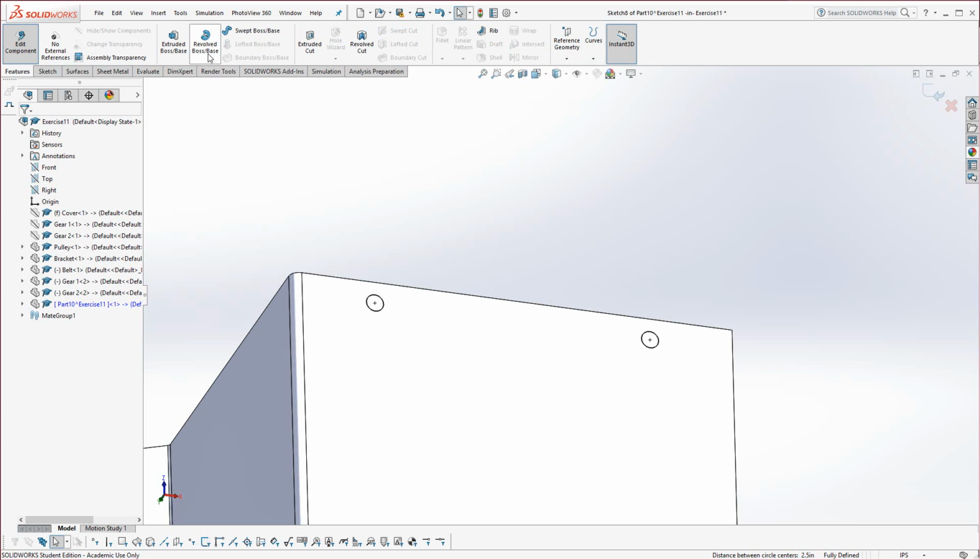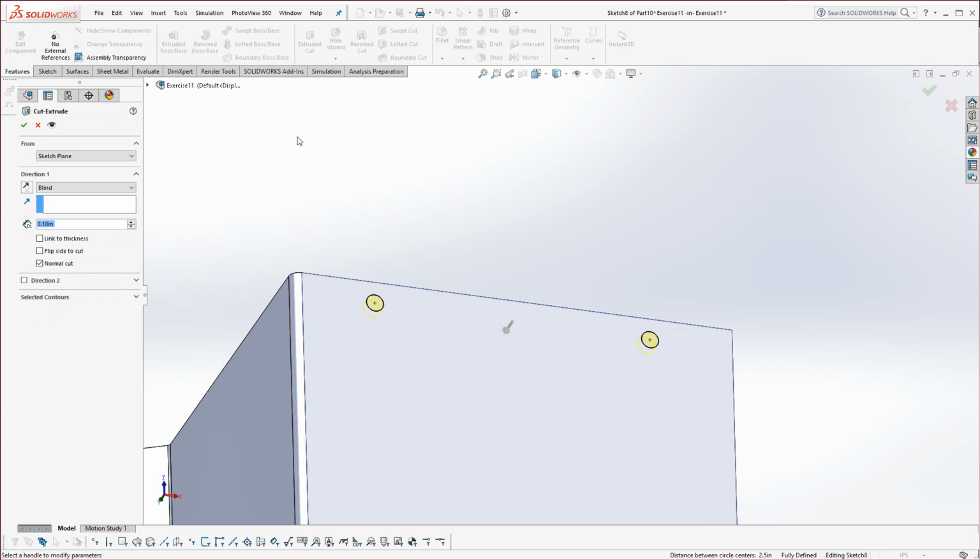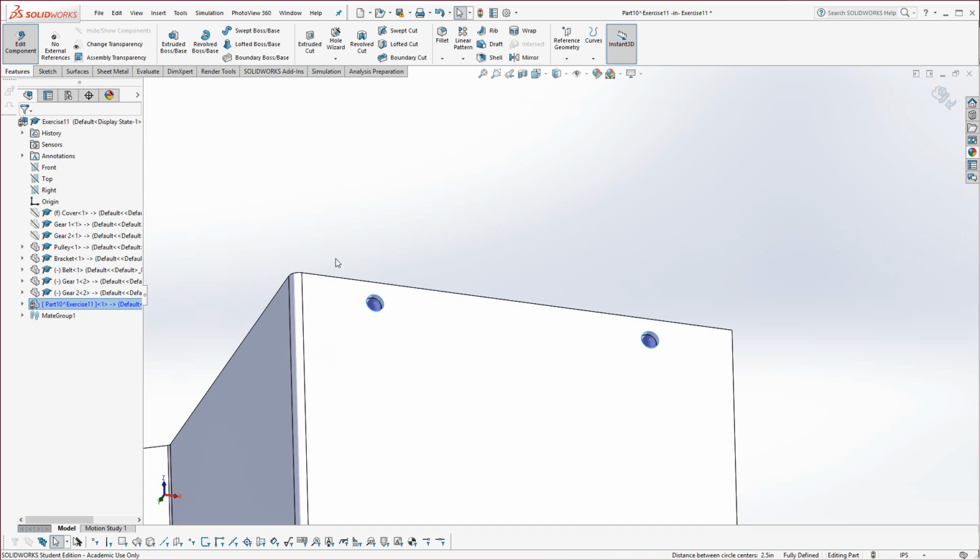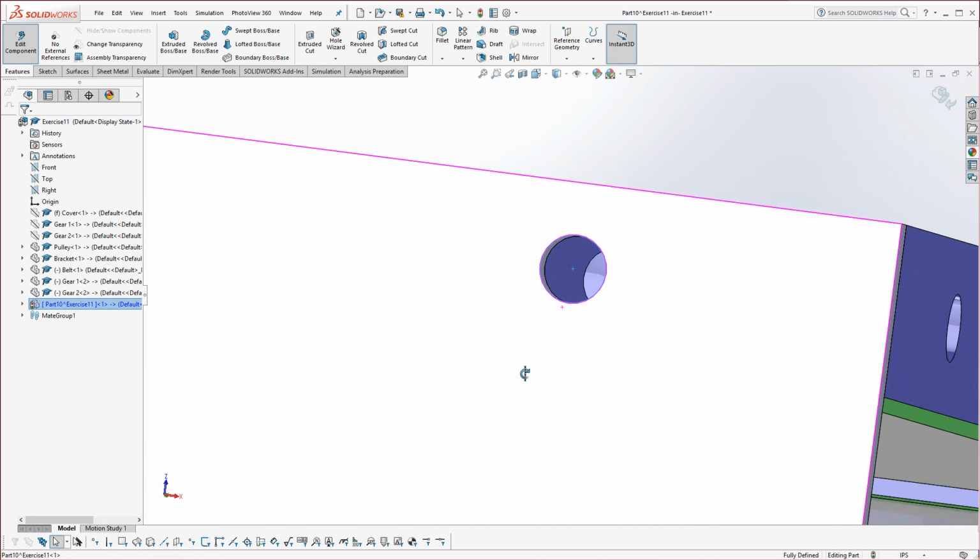Now we could go to Features and Extruded Cut. Now with sheet metal, there's a link to thickness option. Go ahead and select that. That way, sometimes sheet metal folds on itself, but you want a hole to only go through one of the layers. This way, that will work. So instead of selecting through all, select this as an option if you're just trying to go through one layer of the sheet metal. Normal cut, if there's a cut at an angle, or it goes in at an angle in its 3D state. In the flattened state, you can't necessarily cut that at an angle. It's usually cut flat. This compensates for that. Go ahead and hit the green check mark to apply. And now we have the holes, and you can see the holes in there for the fasteners.